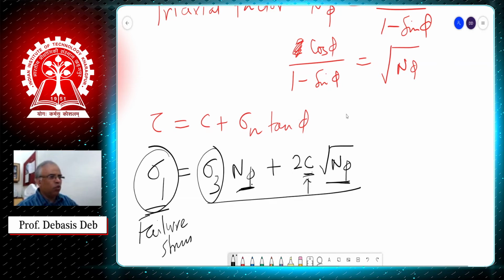That means whatever we thought this material is composed of, and if you want to break it, that friction and cohesion has now come to a mathematical form. So the physical system we were able to answer by the Mohr-Coulomb criterion: to fail the rock, the amount of stress depends on the friction angle, depends on cohesion, and depends on the confining stress. Do not forget about that. That plays a very important role.